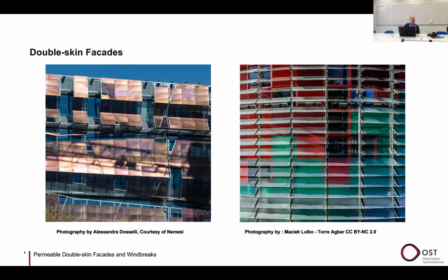So some of you may know the phenomenon of vortex shedding. It is when vortices detach from the building, which can cause oscillations of the building. So these kinds of double skin facades prevent it from happening, or they make the effects much lesser. Another reason why people do this is for energetic reasons. They can provide shade from direct sun. So, for example, the louvers on this tower in Doha can change their angle so that you can protect more from the sun, more or less.